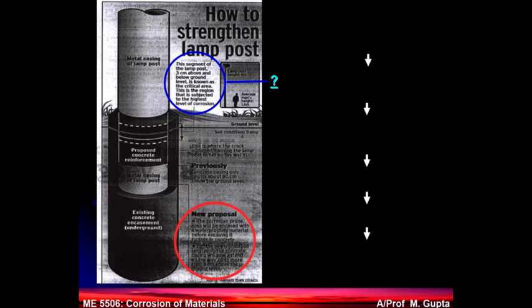But in certain areas like ground level, where the humidity level is high and wet conditions are prevalent, you have a neutral solution, and your cathodic reaction will keep going on at some location. You will keep losing zinc over a certain point of time. And once the zinc is gone in certain areas, then what happens? Now no one can protect iron.